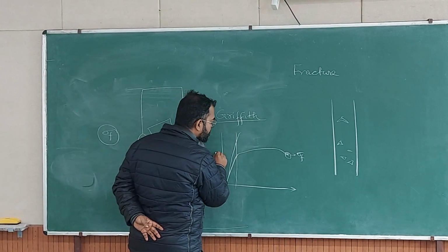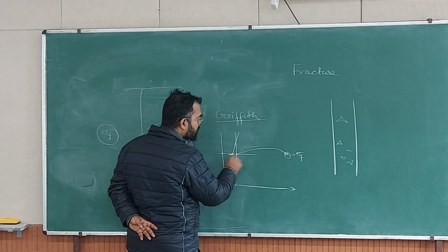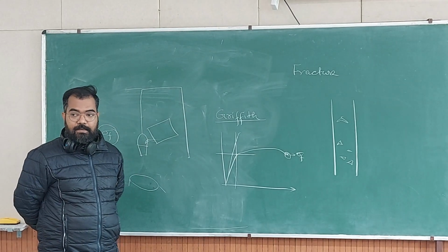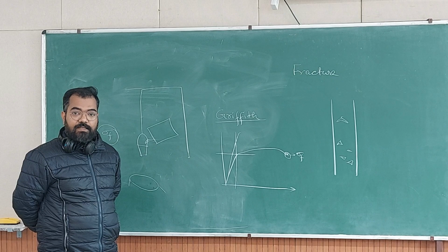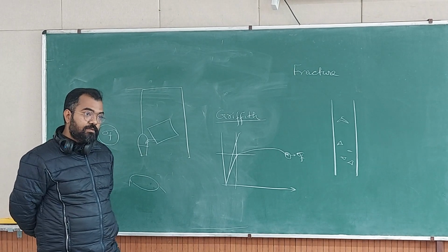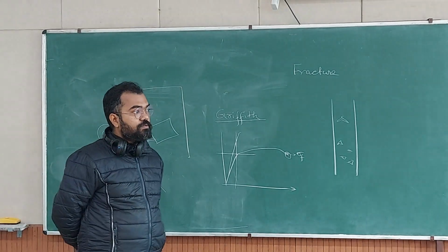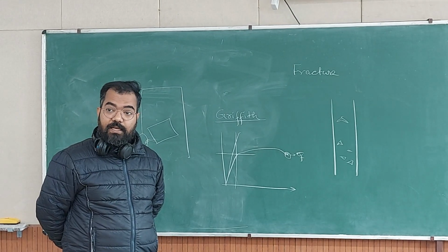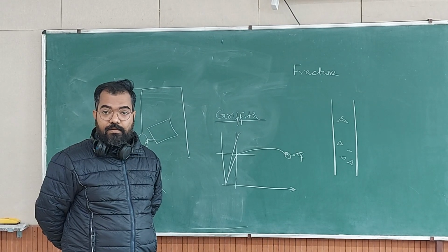At the same amount of stress, both of them will have different amounts of strain. Graphite is not stretching that much, iron is stretching too much, so there is strain incompatibility, and there will be either delamination or the graphite will break.